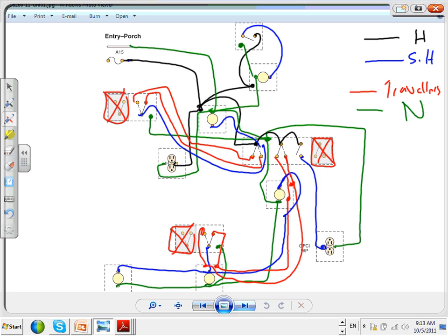Here's a future problem. Take this. That's only in 2011. Suppose I have a neutral with this switch. Does this neutral here count for this switch too? Based on the code, it does. If this switch is powered from a different lighting circuit, on a different pole or actually in the same pole, and you change this one into a switch that needs a neutral, you could easily trip your arc fault circuit interrupter.